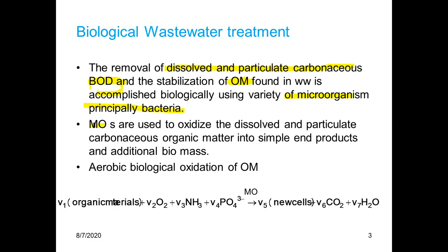Then microorganisms are used to oxidize the dissolved and particulate carbonaceous organic matter into simple end products and additional biomass. There may be non-degradable additional biomass. So the purpose of biological wastewater treatment is aerobic biological oxidation of organic matter. This is the reaction involved in the aerobic biological oxidation of organic matter.